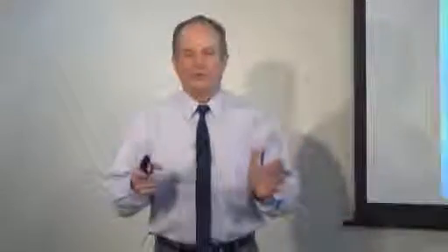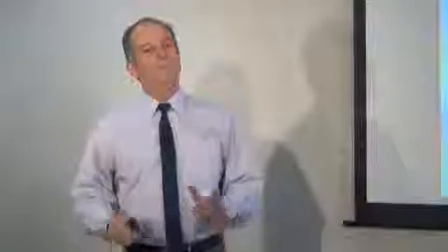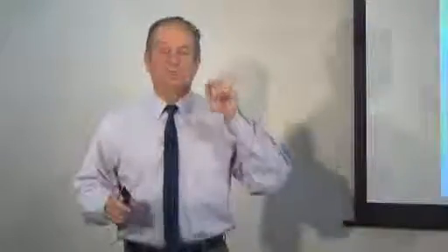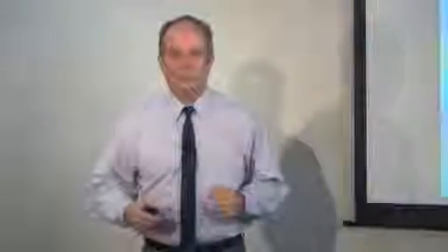When you go leading or lagging, you are doing a couple things. More current. Well, more current on a system, what does that do? It causes more voltage drop. Well, what does that do? It gives you voltage collapse if you're not careful. So we're trying to minimize VAR flow to minimize current, which minimizes the losses, which minimizes voltage drop, which improves voltage stability. I hope all that kind of comes together because that's really the crux of all this on a three-phase power system. Okay.